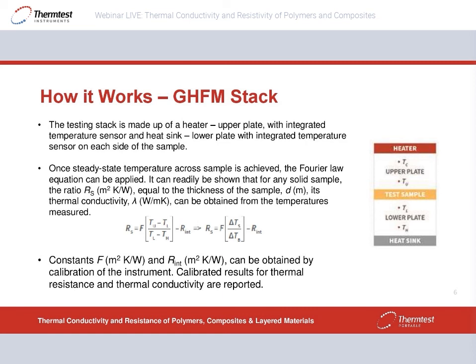This is a calibrated device. The ASTM standard and this method requires a contact agent between the plates and the sample, and we would calibrate those away. That can be done by the user and or the factory, but the effects of that added contact agent is calibrated away. So once we calibrate that away, we're looking at the thermal resistance of the sample itself. Once we know thickness, the thermal conductivity is also reported.